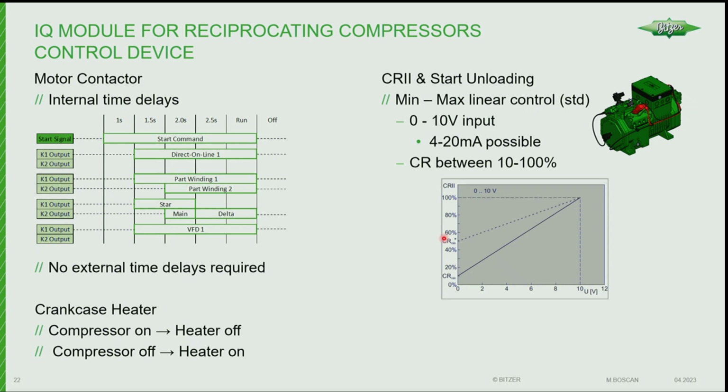Again, we don't want to shut down the compressor, and if we don't get mass flow over the motor, it will shut down on motor temp eventually, so it will go through that cycle indefinitely until you increase the 0 to 10 signal, and then it will load back up. So you may see that if it's off long enough. If you're at 10% for that long, you probably want to look at the controls and change that because the compressor is not very efficient.